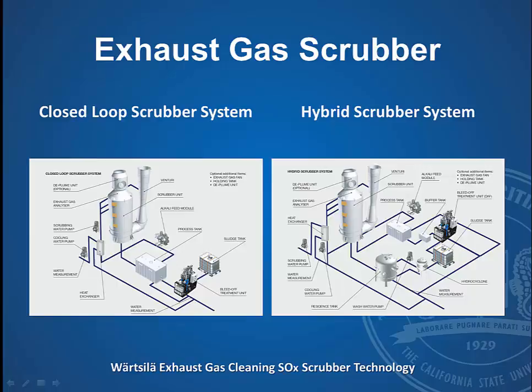You will have a small amount of water that is being continually brought into this system, and there will be a small amount discharged over the side. But again, this is designed for use in a freshwater system, and it will minimize the amount of acid that is being discharged overboard. And then with a hybrid, it can be operated as either an open or a closed system.